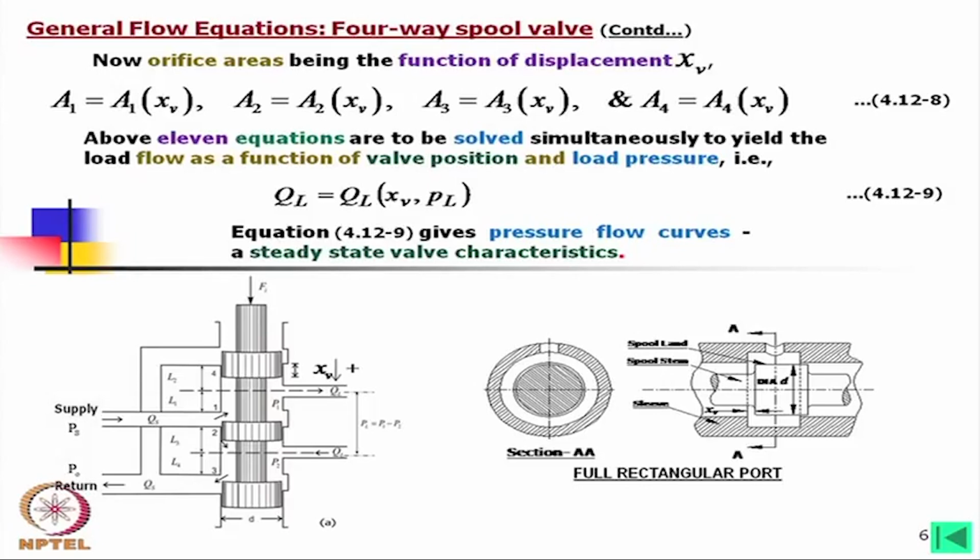but in the vicinity of the operating point, depending on the speed, suppose we are moving an actuator with a load and with a certain speed, that means we need a certain amount of flow. The same flow might also be used to move at a lower speed. Depending on that, we will first open the orifice to the extent to have the desired flow.